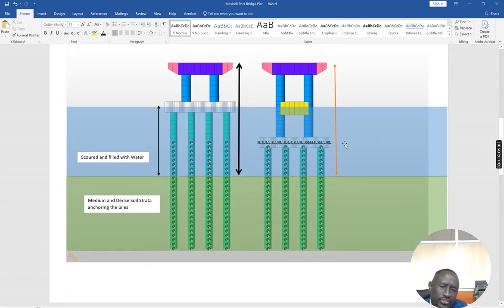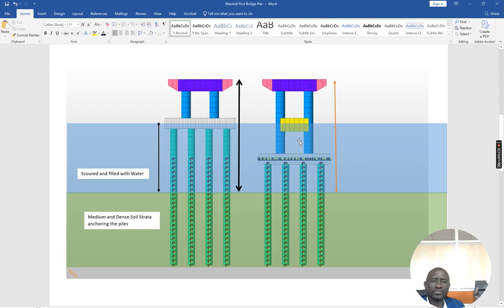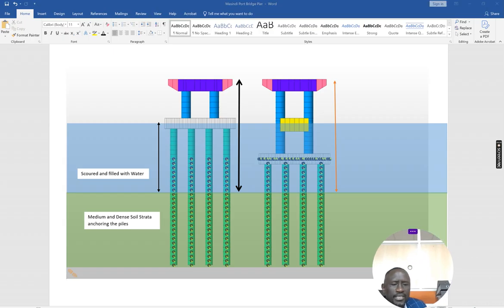So this is the situation now. Scour has happened. So someone needs to do analysis. You need the loading to remain the same. You need to reconfigure your soil structure interaction. No more stiffness simulation, I think, in this zone. You have to bring it down to where the soil started going down, and therefore there's going to be a change in the response by this support system. These are two different scenarios.